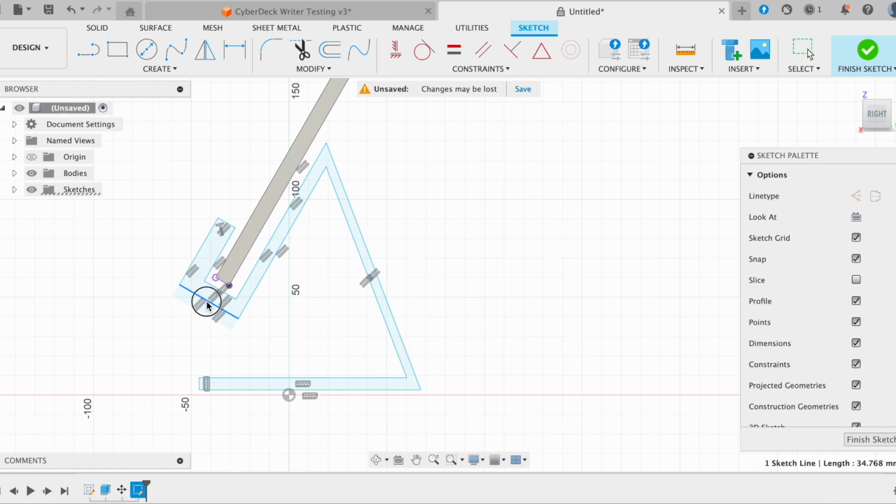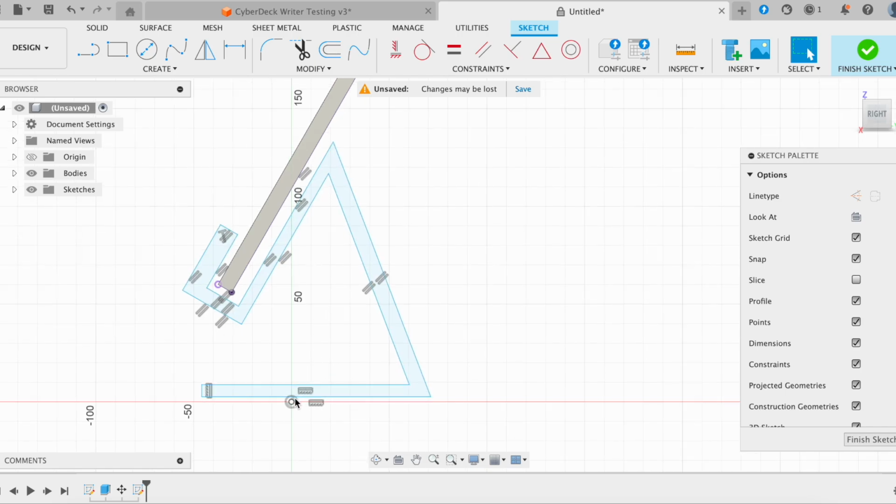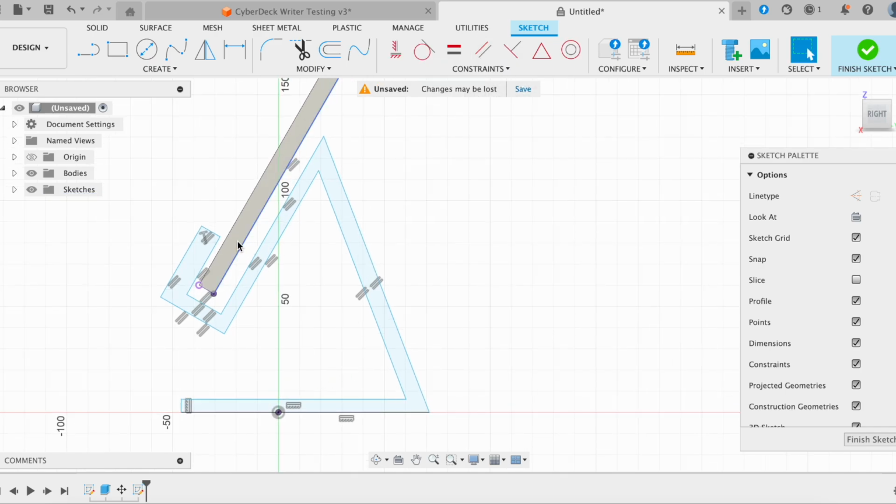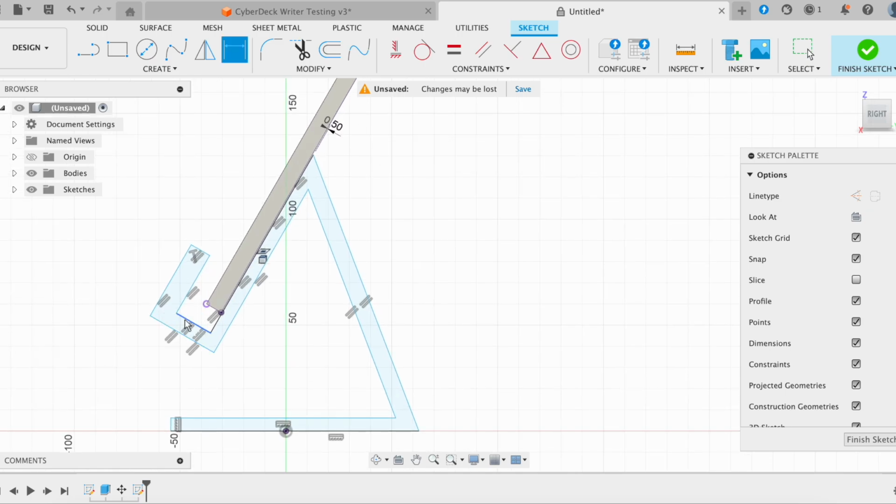That looks good. And now that we have this general shape, we can go ahead and try setting some dimensions. One thing I'm going to do is make sure that this bottom line is snapped using the coincident tool to the origin. And then I'm going to make sure this line is also very close to the phone by setting a dimension of, for now we can just say 0.5. It really doesn't matter, you could even snap it closer, doing a really small number.